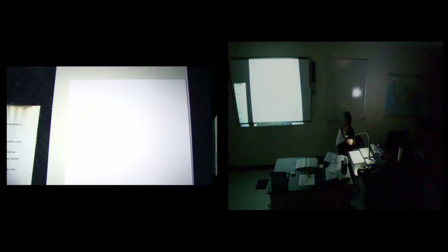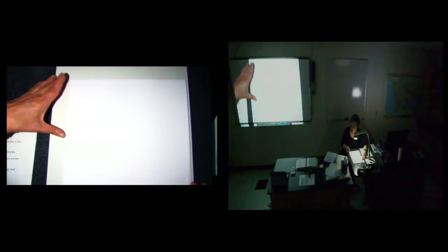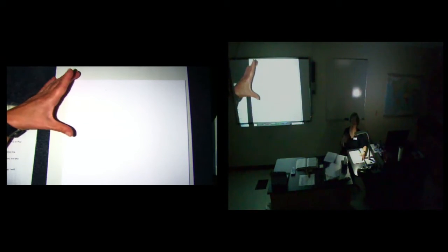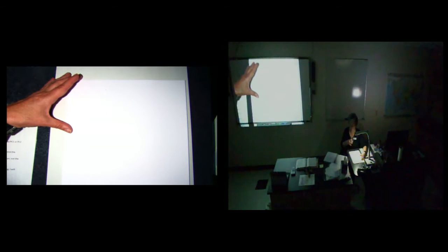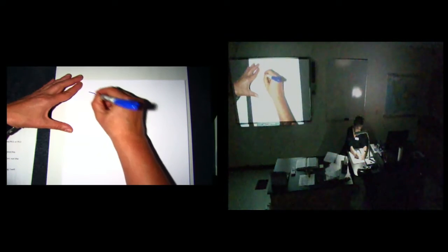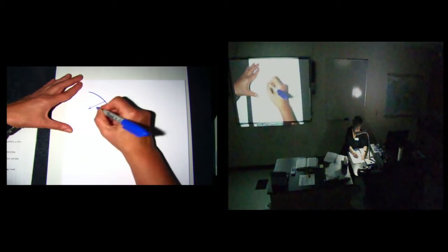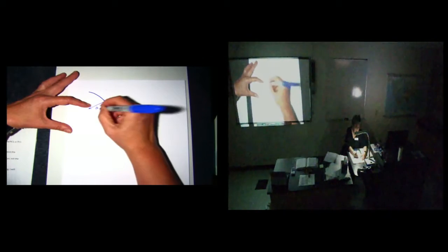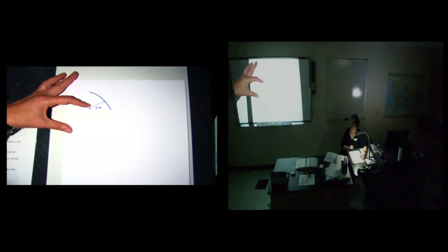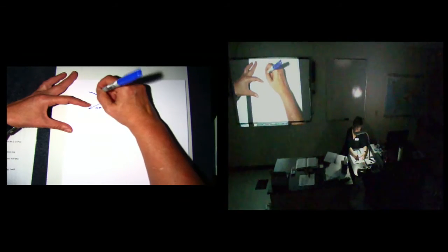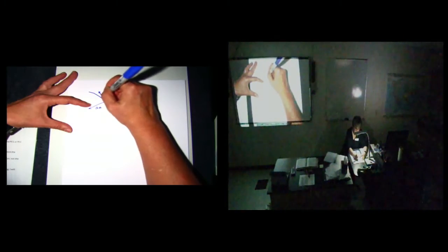Okay? And if I do that, and I'm looking at a velocity as well, my velocity can be written as the magnitude of the velocity with a unit vector tangential to the curve. And that's just another way of writing my velocity. We also know that velocity is going to be my change in position with respect to time. So now let's take it one more step, and now my acceleration is my velocity with respect to time, but if I'm doing that with this component right here, I'm going to be taking this derivative with respect to time.